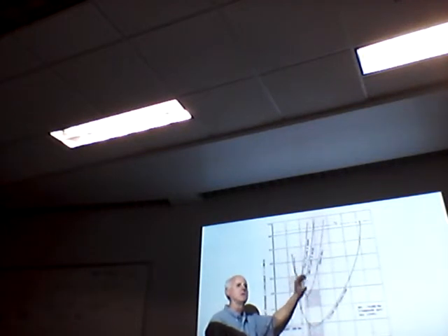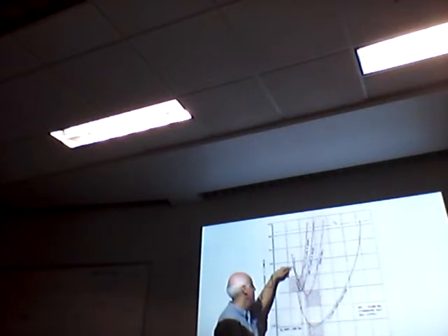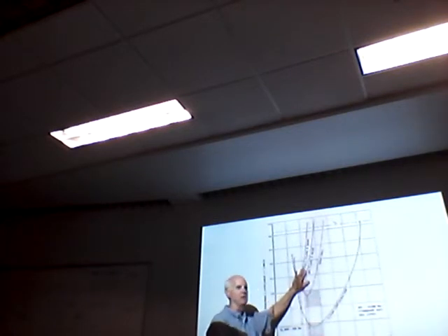Does it make sense? So if the gear goes down, what do you expect to happen to the curve? It's primarily parasite drag, so this side of that curve is going to be more steep, right? You can see how these curves change with full flaps and gear, say 60 flaps. I would simplify this and make it a little bit different.